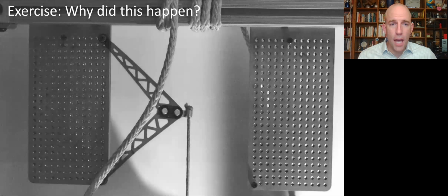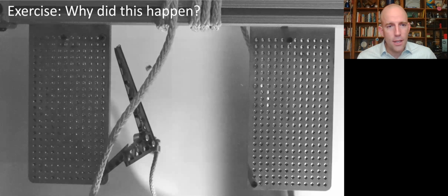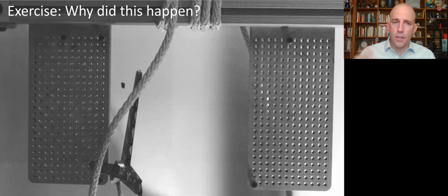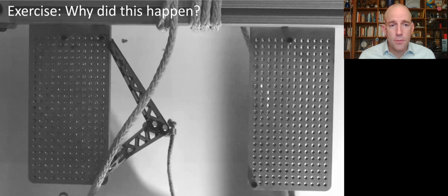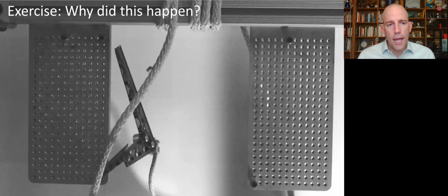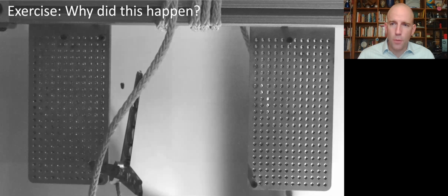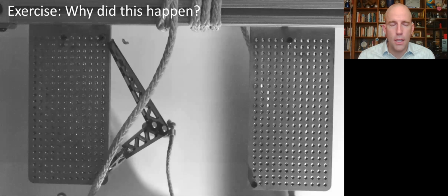Here's what actually happens. So once again, it looks like maybe some out of plane buckling, like we saw in the last example, but the fracture is happening at lots of places simultaneously, and it's probably starting at one of those sharp internal corners, which are likely to be big stress concentrators.